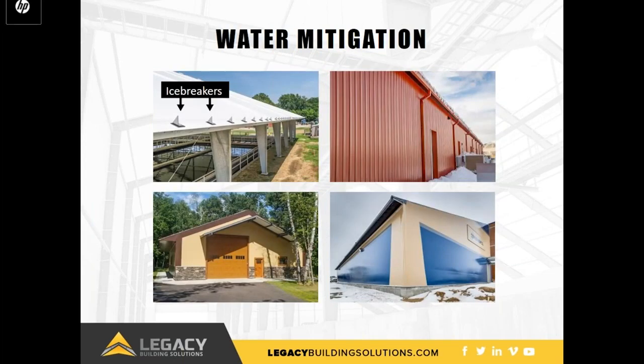Gutters and downspouts may be added to the overhangs to divert the flow of water and provide a dry area around the building. In many situations, a water management system is required to provide a safe walkway, meet airport regulations, or to protect landscaping or other surrounding features. We mentioned earlier that tension fabric is designed to help snow slide off the roof. Many legacy buildings' designs also include icebreakers, which break the sheets of snow and ice into more manageable chunks before they strike the ground.